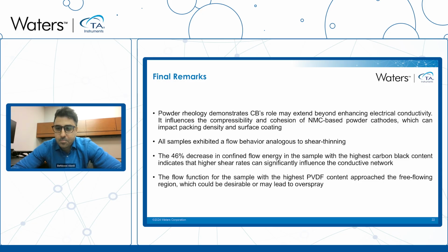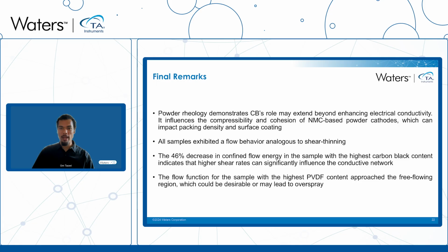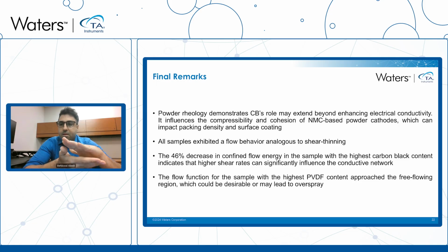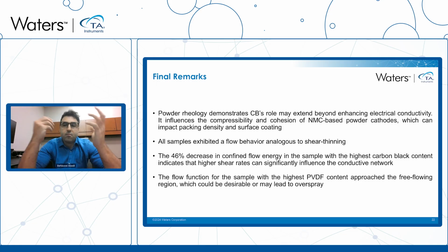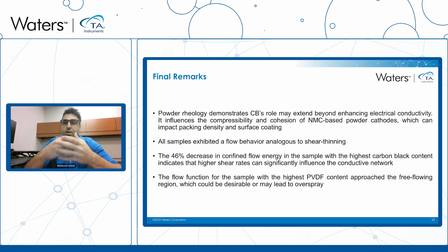Fantastic. Our next question is, what is the recommended temperature soak time for powders? Oh, yeah. When you do rheology, you do the test between very small gaps. So the volumes are lower and the liquids are better conductive for temperature. In powder rheology, you do like 20 cc of powder. So you need a higher temperature soak to reach the steady state. We normally would recommend half an hour for that.